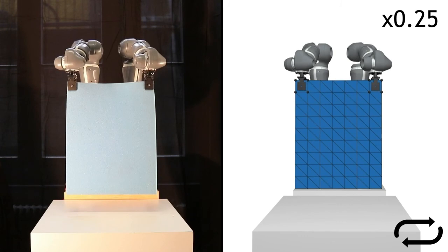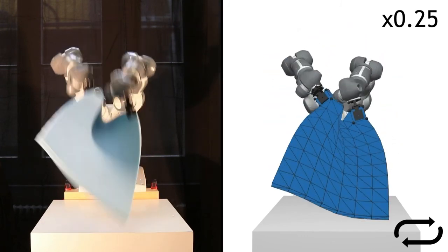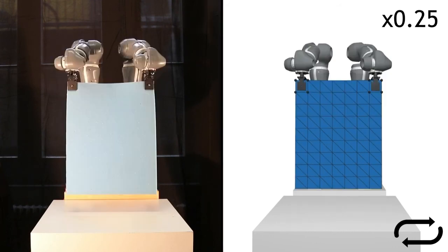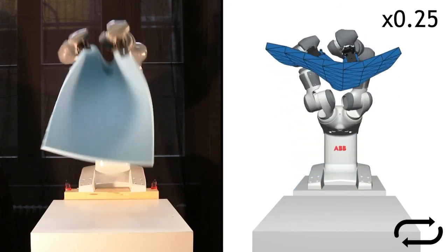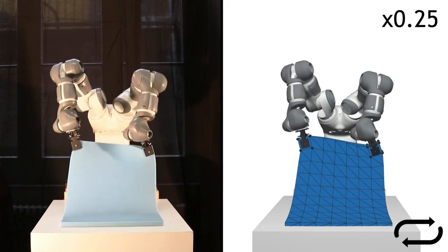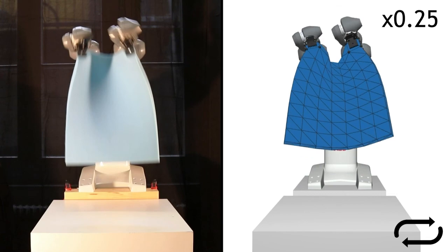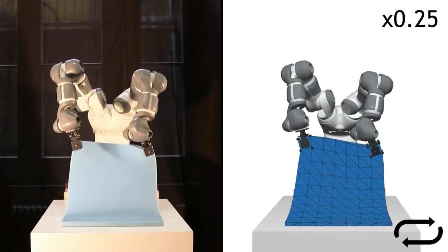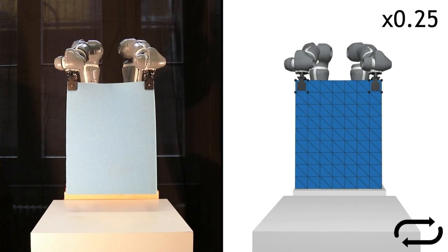An example of such mismatches can be seen in this side-by-side comparison. Although the robot generally succeeds with its task, it can be seen that the simulation model predicts that the lower end of the soft sheet will lift up higher than it does in reality. Recently, methods have been presented which track and analyze the motion of physical prototypes in order to accurately reconstruct their material parameters. How to include these techniques into our framework to further reduce the reality gap will be part of future investigations. Another interesting future avenue to cope with these problems is to include feedback control into the current feed-forward process. How this can be done best is a research question that deserves its own investigation.